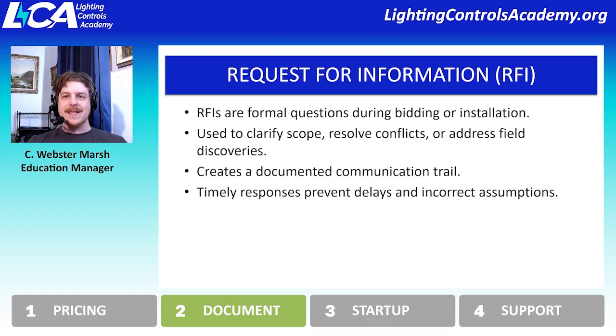If the RFI is sent out and work continues in that area, with an assumption that the RFI is going to go in a certain direction and that assumption's wrong, then there might have to be rework. It really depends, but oftentimes RFIs are just going to screech everything to a halt until there's a response. So responding quickly and effectively really helps smooth that process along.